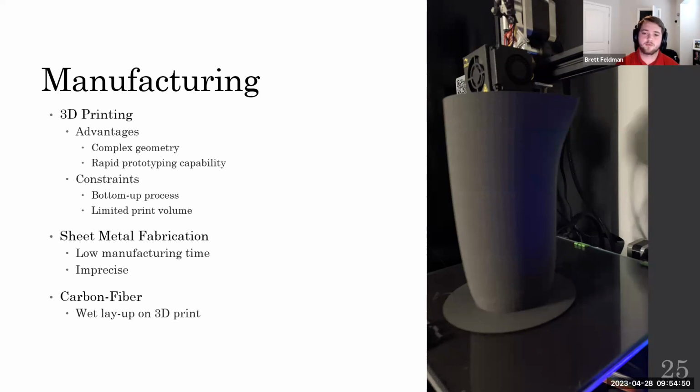3D print. This was to minimize material as well as time on the hot wire CNC and vacuum bagging. We chose to go with 2 layers of carbon fiber as well as epoxy to adhere them, and we just wrapped it up and let it sit overnight. The results were relatively similar to what we have seen in demos for the hot wire CNC and vacuum bagging, so we thought our print was acceptable.